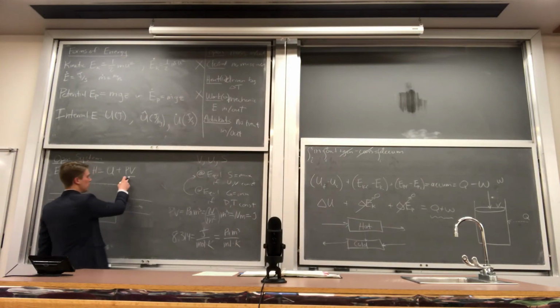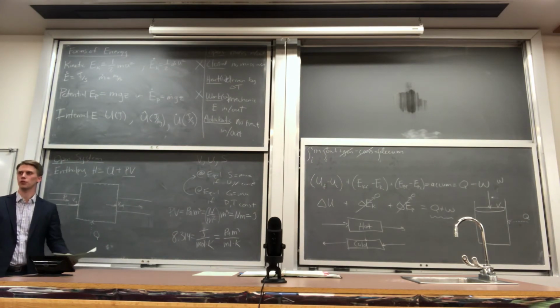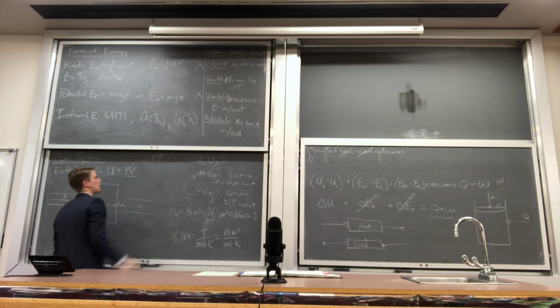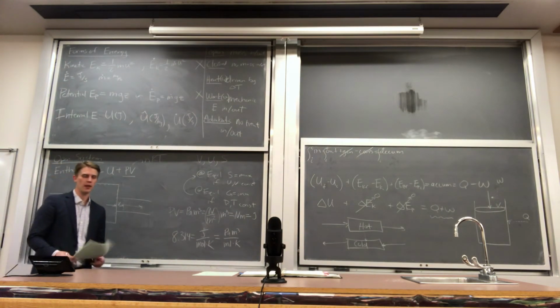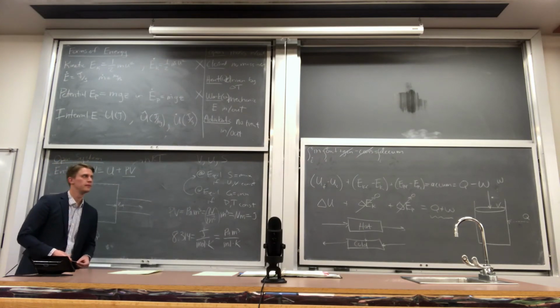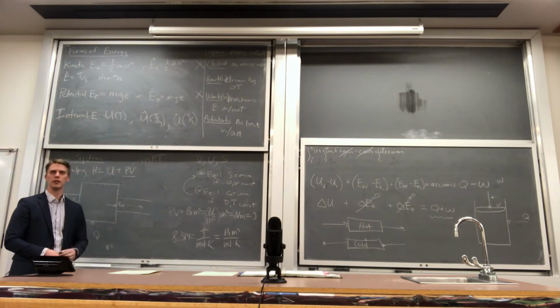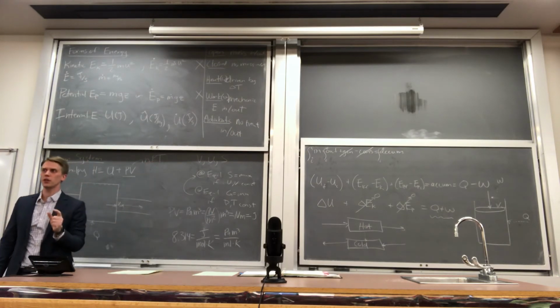Now let's think about this PV for an ideal gas. What is PV equal to for an ideal gas? nRT. For an ideal gas, what is the enthalpy a function of? Temperature. It's only temperature, right? For an ideal gas, the internal energy and enthalpy are only a function of temperature.